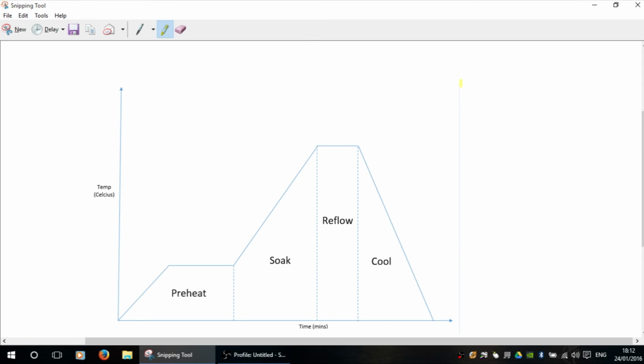If you live somewhere that's rather warm and hot versus somewhere that's cold and wet like the UK, that can also lead to differences in humidity, which encourages moisture into the board, and a humid environment has lots of moisture. If we put too much heat too quickly into the board and BGA, then we can ruin things. If you live somewhere that's very hot, the board will absorb heat from the environment a lot quicker than it will here. So you may find that you don't have to put as much heat into the board as I do, and in doing so you may end up with your chips popcorning or damage to your board and other components. And again, I don't want that for you.